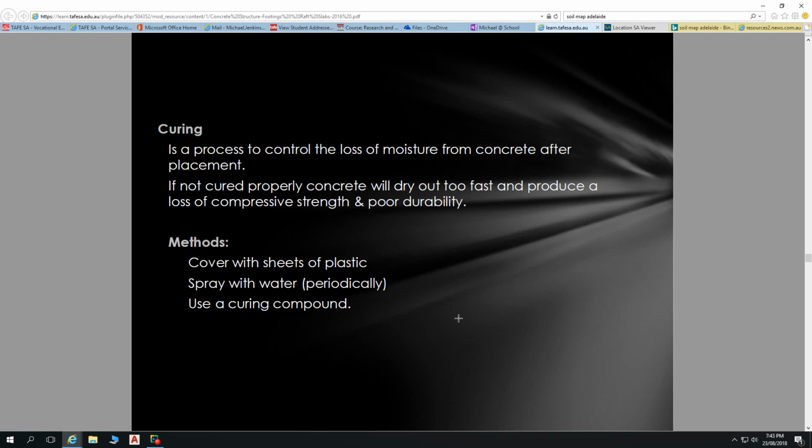So timber boards that have a rough finish to them, you use that as your formwork. Pour your concrete in there, pull the timber away, and you see the grain from the timber expressed on the concrete as well. So there's all sorts of different things you can do with your formwork to get expression of different things. Another thing is concrete stamping.